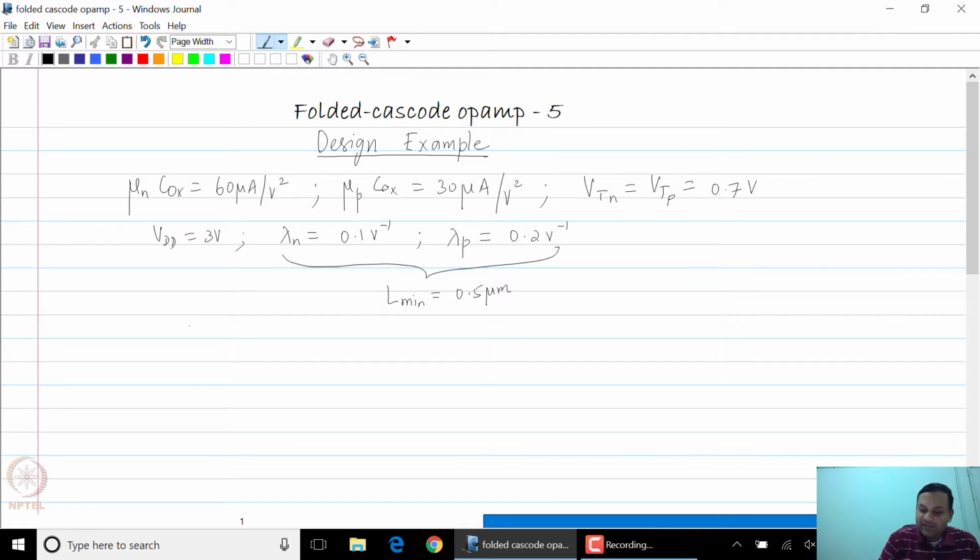And the requirements, so design conditions. To make our design look more like a real world design, we are not going to over design, over constrain, because we want to come up with an initial design based on some smaller subset of the real world conditions. So let us say that we need an overall gain of 2000 and the swing limit, so let us say I need an output swing of 1.5 volts peak to peak,